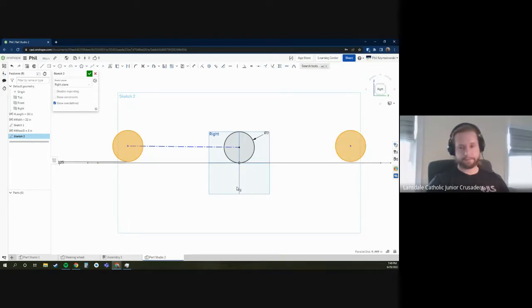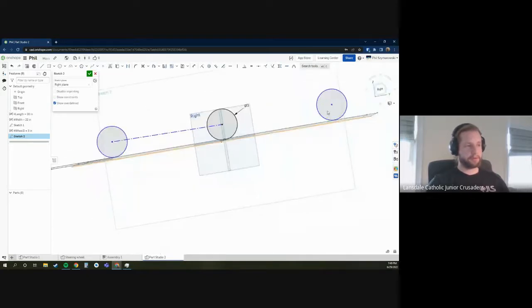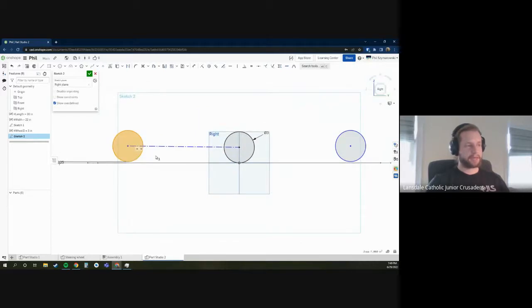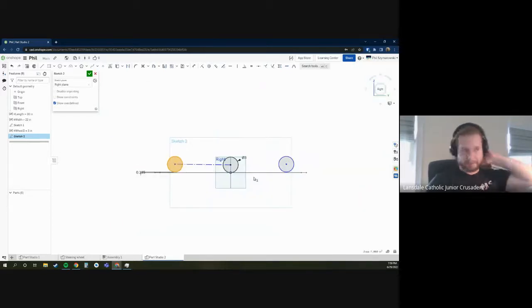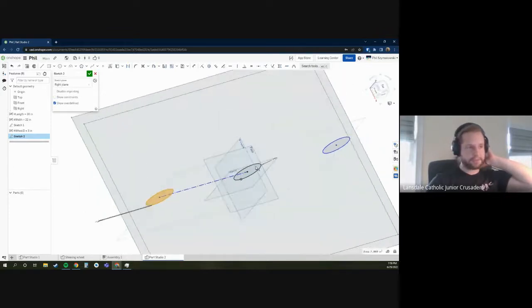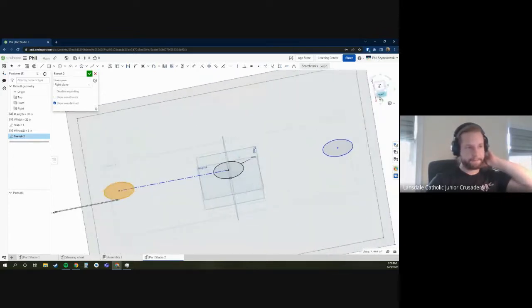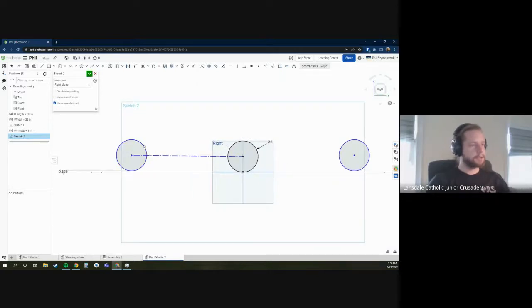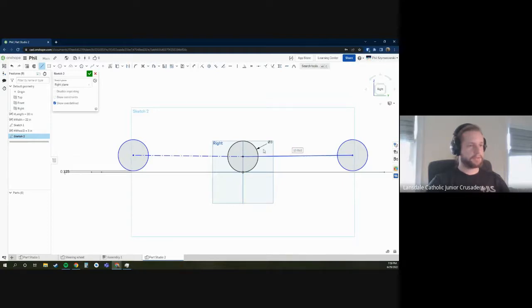wheels. Okay. And remember early in our first thing we said we should always design things as if they're centered on the origin, which our robot is right now, and that the wheels are on the ground, or whatever we're designing is on the top plane, which is exactly how I'm designing it right now. So now we've got 2 wheels that are exactly 1/8 inch off the ground, and they have some center distance to them each, and I can draw one more line between this wheel, even though those lines are the same length. Make it construction geometry.